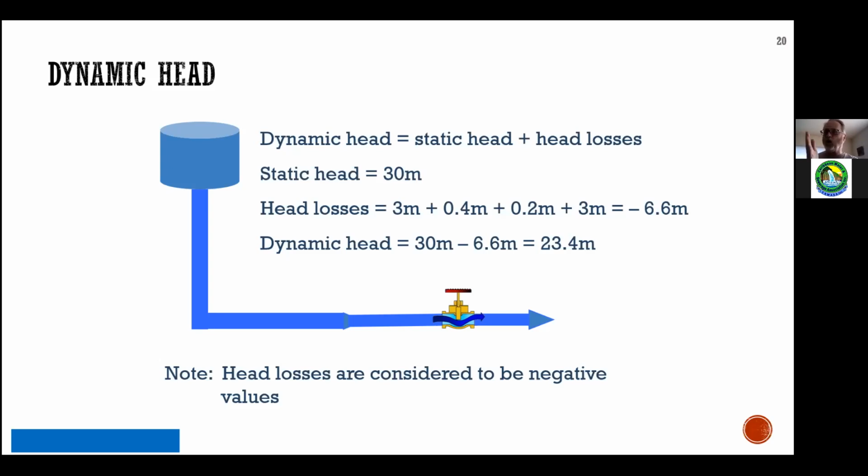More than one, or one valve in a critical location, can basically negate the entire supply. And then the fire department doesn't have enough supply for an emergency, or the agricultural sector or the commercial sector can't do their work because the system has not been configured, or operated, properly.